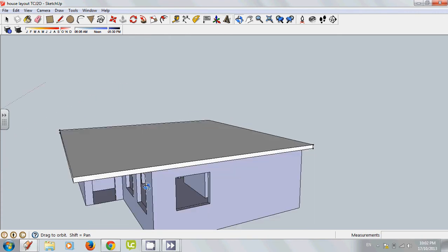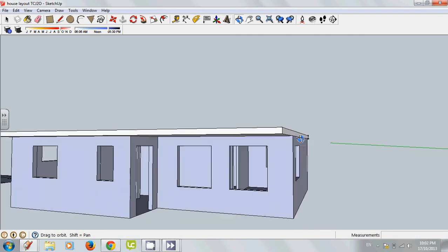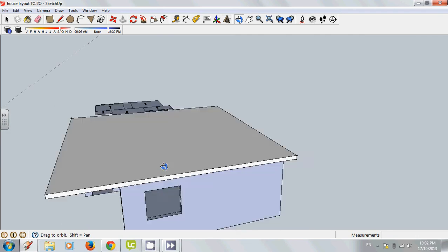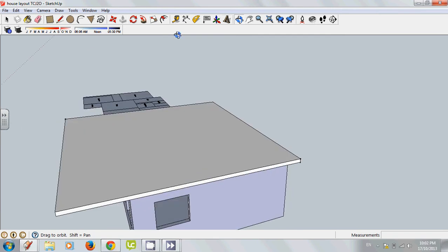So now we've got this platform, and we're going to put our gable lengthwise down here. I've got to decide what I'm going to do for a slope here. So I've got a width of quite a few inches, so it's narrower this way. So I'm going to go with a 5/12. So I'm going to come across here 12, which is the run, 12 feet. And I'm going to come across this side 12 feet. And then I'm going to come up 5. So the rise is 5 and the run is 12.